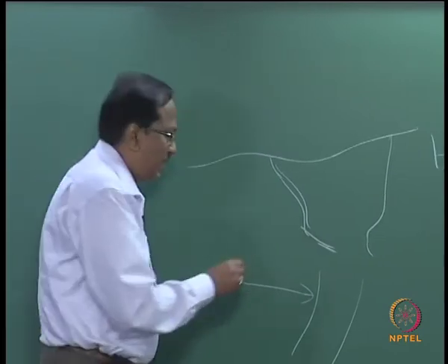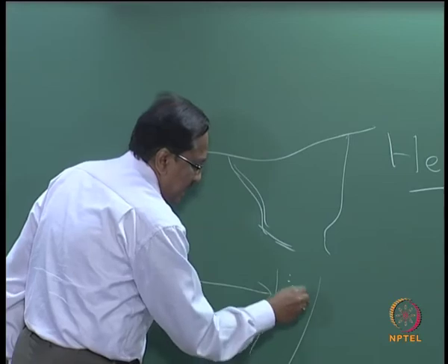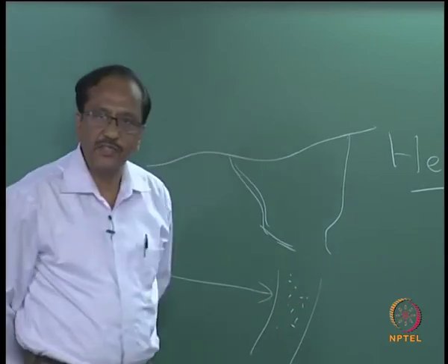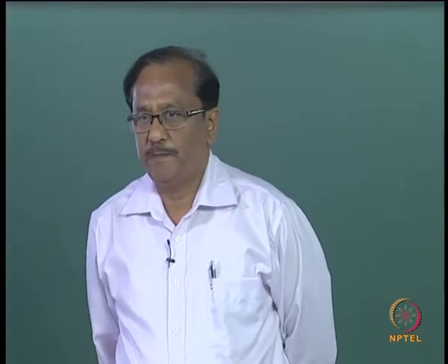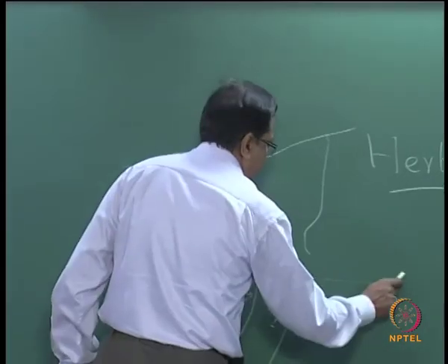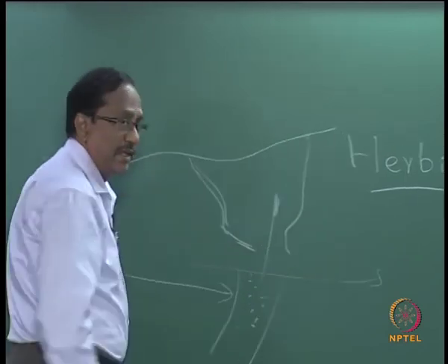What will happen? If the fall velocity is high, the coarse sand will simply settle in the approach channel. But if it is very fine, the sand will either go straight or maybe also enter the harbor.